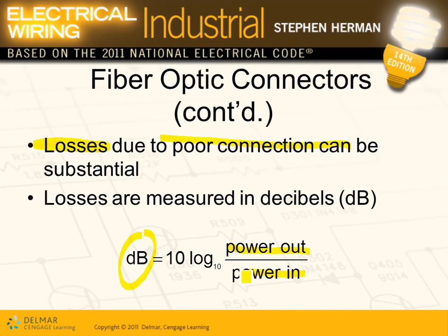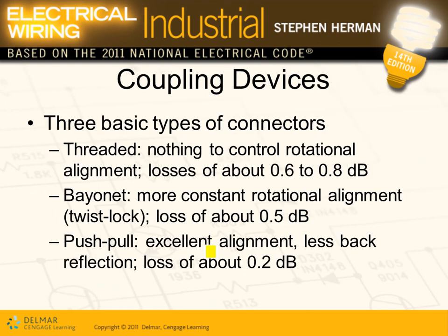So Adam, this is the efficiency of your cable. Can you guys see that? The efficiency of your cable is power out over power in. Any comments, Karen? Any questions? Did they put you to sleep, guys? No? Any comments, any questions? This is a good topic though. dBs, so they take the log. I don't know how many of you have a scientific calculator. You can measure these. Take the power, take the log 10 of it, multiply it by 10, and that will get you the dB for the system.